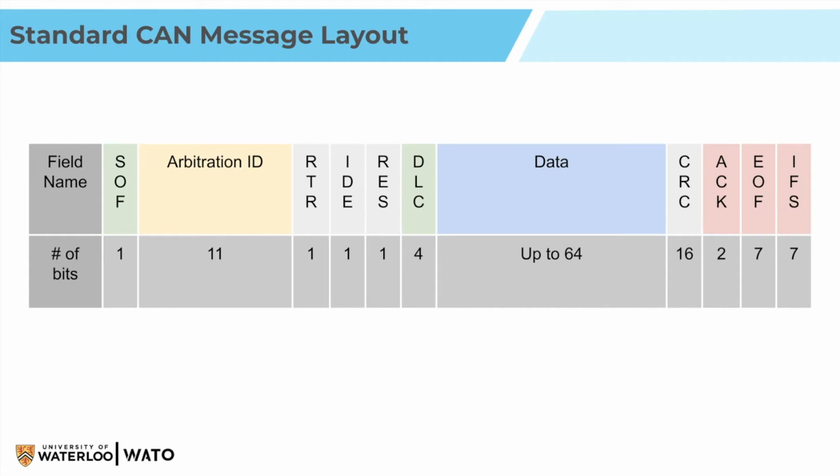This is going to make sure that your message is fine, and there's going to be checking for transmission errors. Different systems can implement the CRC a bit differently. I think the way that GM has provided it is by using something called a checksum. So you sum up all of your data, and then you take the 2's complement to make sure that your data looks right and you're transmitting it correctly.